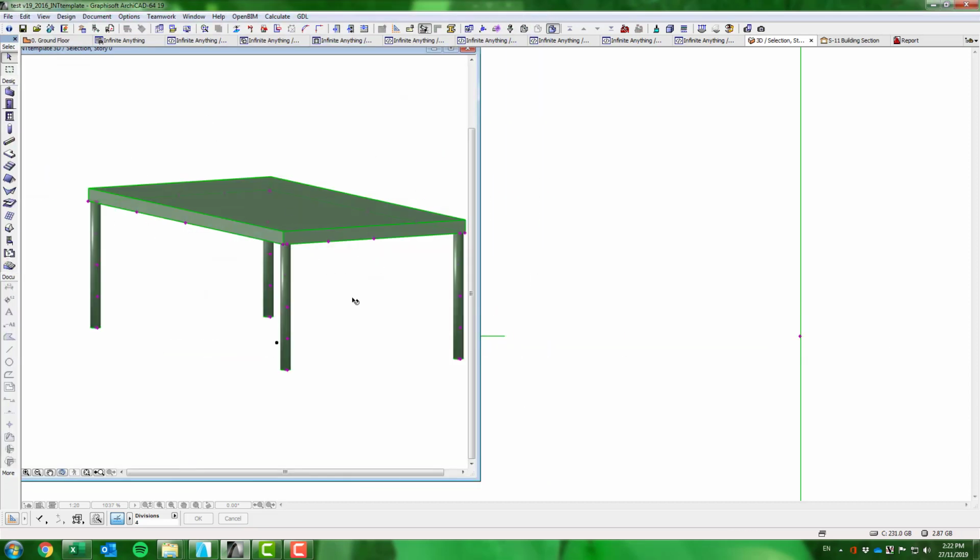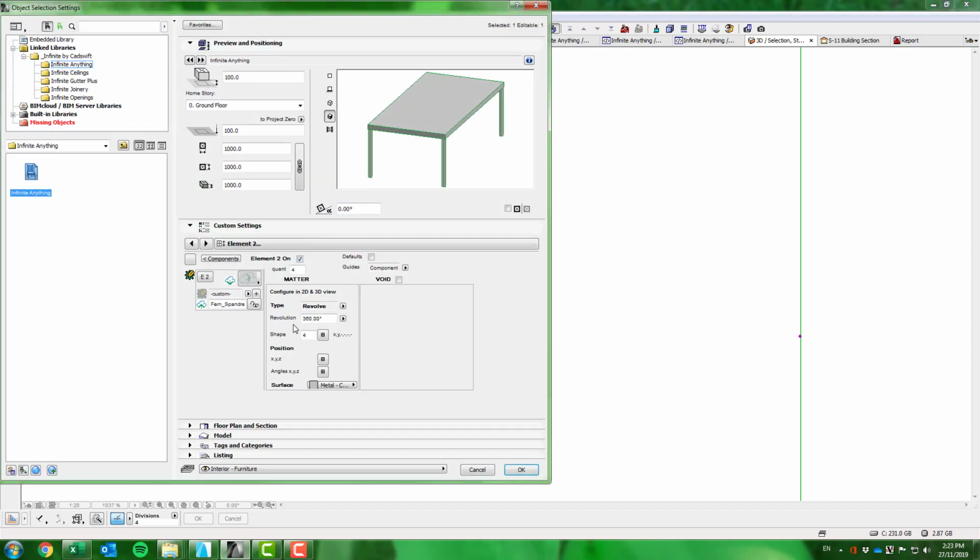Now you want to save that element, and we might want to save the leg type and the tabletop type. You can do a tube around that in the void if you wanted to actually put a profile on that edge. So you'd turn on this void, you'd select tube, you'd nominate the profile of your tube on screen, and then you wrap it around. I'll show you how to do a tube shortly, actually. Actually, maybe I'll do that. See how well it works.